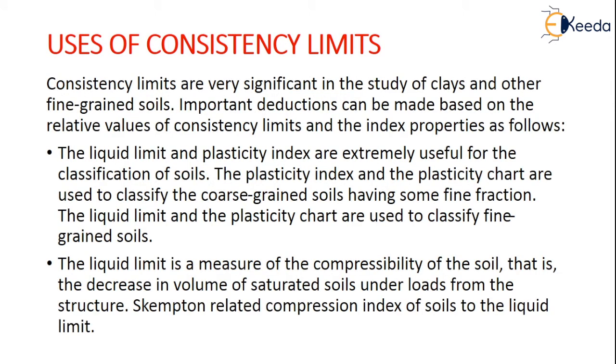Consistency limits are very significant in the study of clays and other fine-grained soils because these are the important deductions which are made based on the relative values of the limits and the index properties, as follows. We have different limits like liquid limit, plastic limit, etc. So let us see how each and every limit is important to calculate the corresponding important factor. The liquid limit and the plasticity index are extremely useful for the classification of soils.